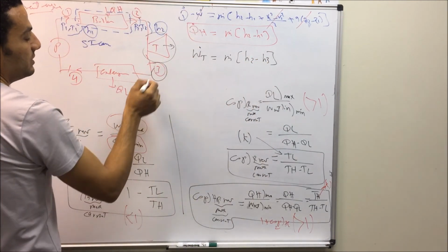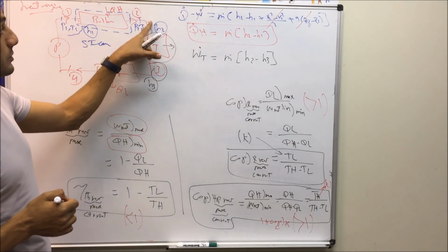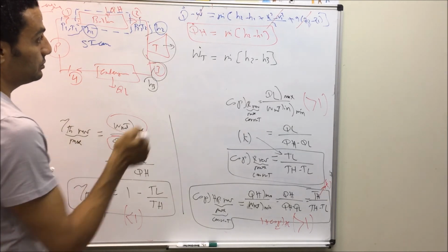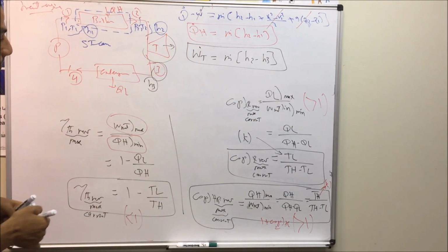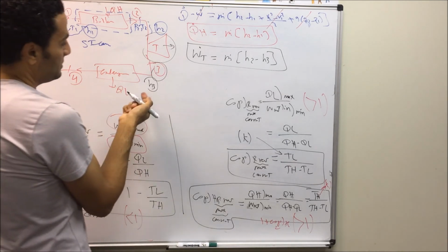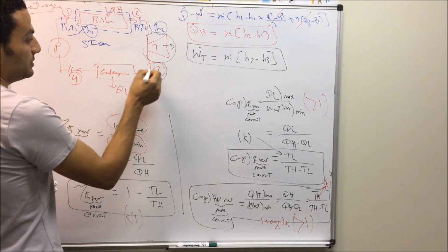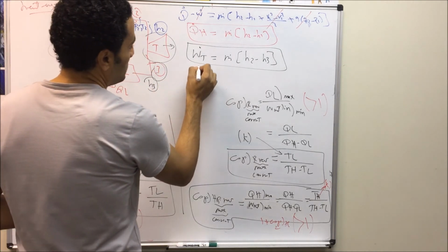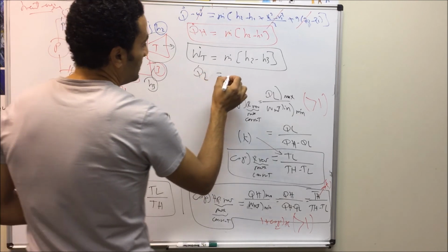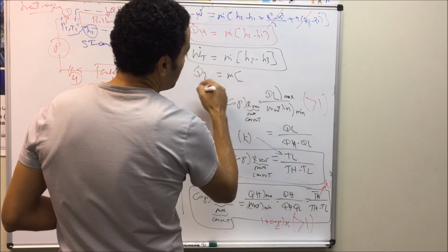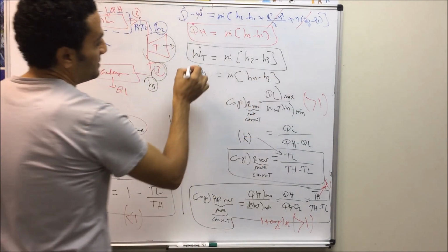So using the table you can calculate H3 from the condition at point 3, and also from the condition at point 2 we can calculate H2. So if I need the work out of this turbine we can calculate it. Also in case of the condenser you may be given the condition at point 3 and point 4, so Q dot condenser, which is called the Q dot low, will equal to M dot, the mass flow rate of steam, multiplied by H4 minus H3.